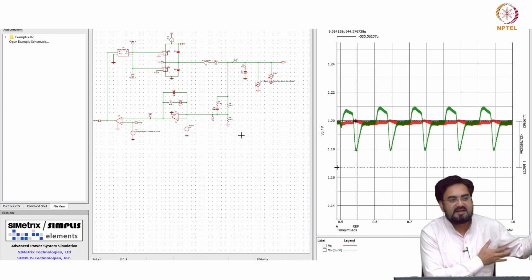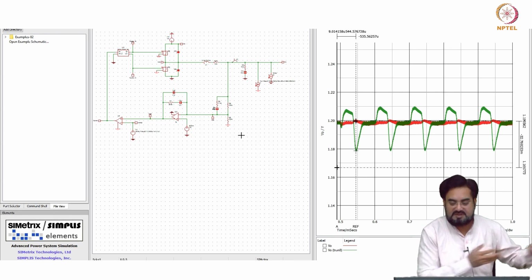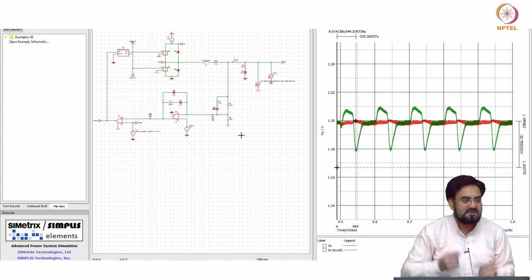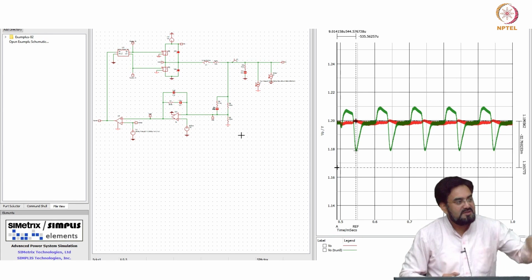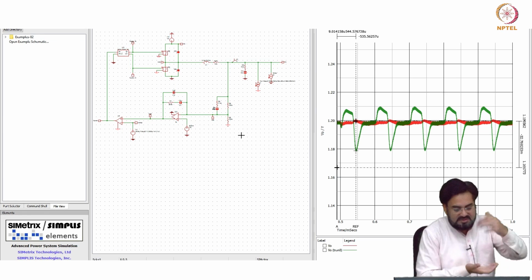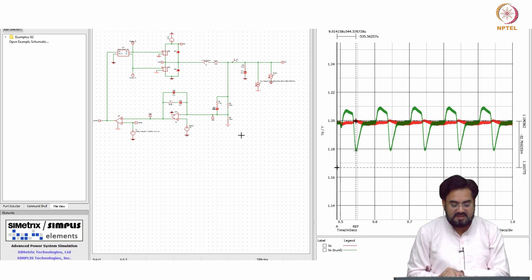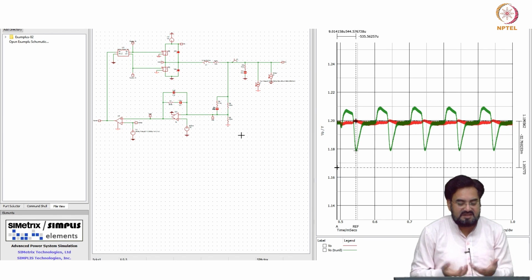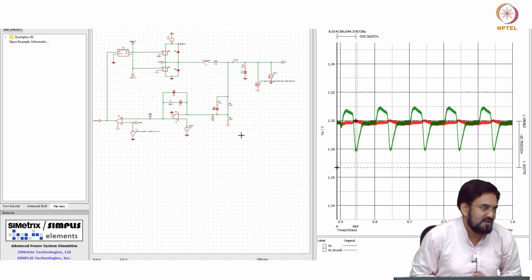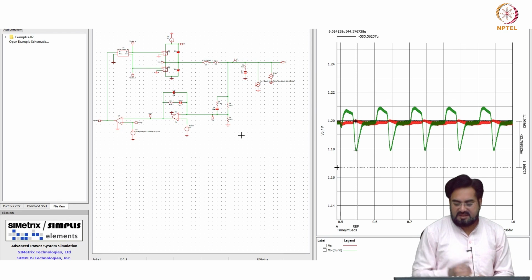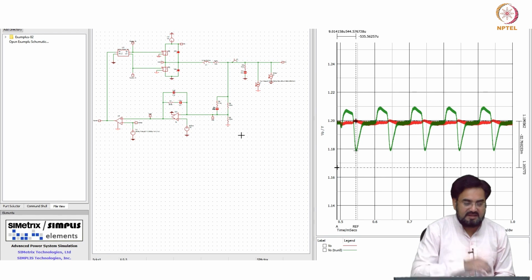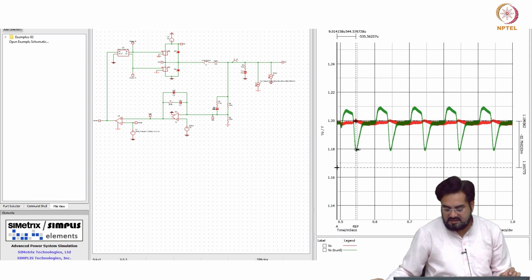If you look at that gain, we are getting 100 times, which means this should have been on the order of maybe volts also, but it is not large because it will get suppressed up to some point by the loop gain. That suppression will depend upon how much loop gain you have in the feedback, but it may still appear if you do not have those poles added in your compensator. Okay. And you can see here, we can measure this peak to peak.